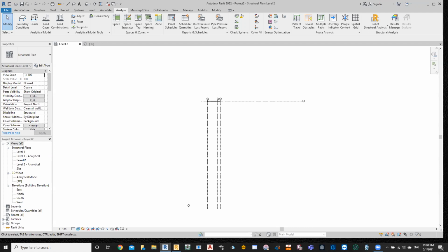Sir, I want to ask you. In our project, we have the column in the ground floor, and it's more than the first floor. What do we call it? Floated column. Yes. Floated columns are columns which are available in a level, but they don't connect to the foundation. They don't have a foundation. They act on a beam only, and they will stop. Okay, that's fine. You just specify your column is available.